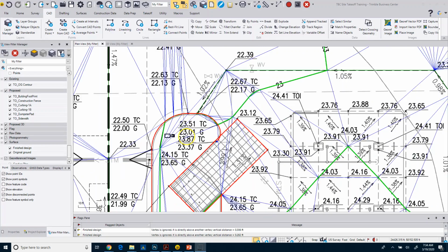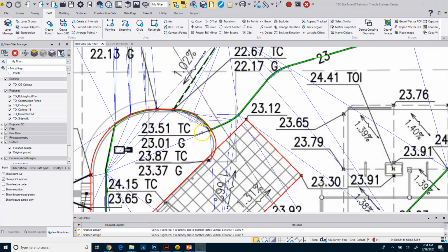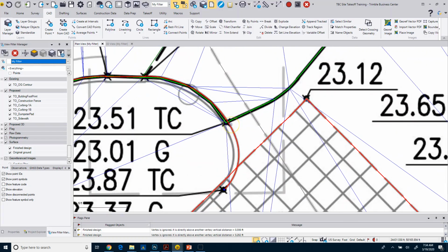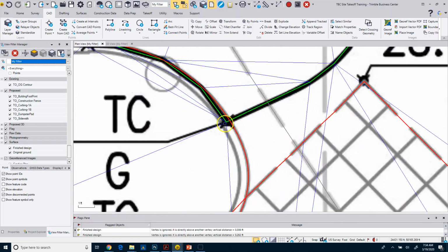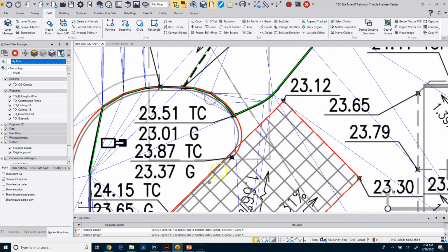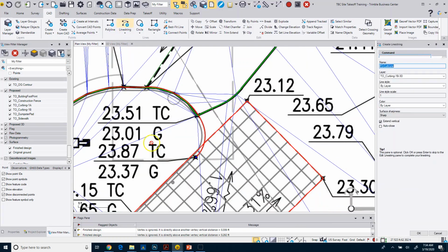All right, so now as I started getting into drawing in this curb line here, I noticed that there's one, I made a mistake earlier, so we're going to fix that. And two, I want to make sure that we go about drawing this the right way. So you can see here, this 23 comes in, it's 2301 at this particular spot. So the contour is back here, and that line crosses over there. So what I want to do is I'm going to draw this line. And I just want to show you this to pick up some additional tips. We'll adjust this elevation once we do this.